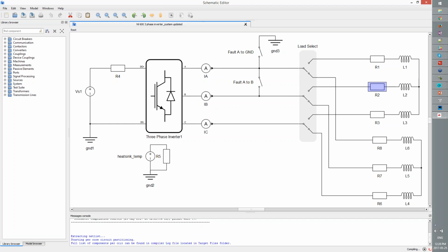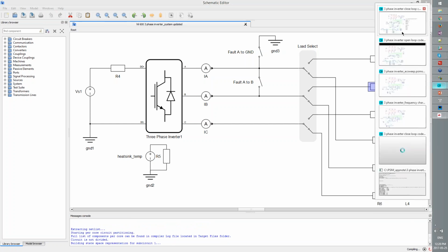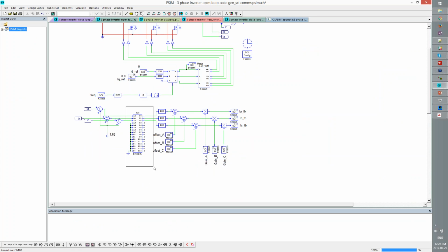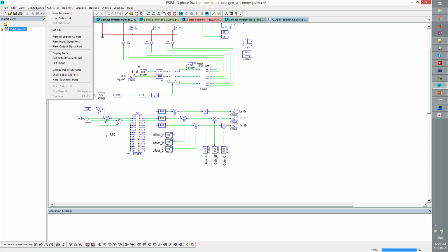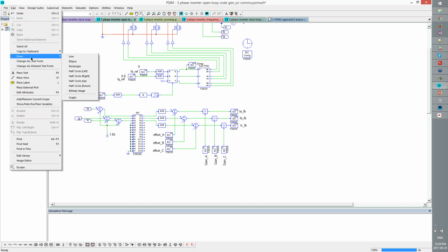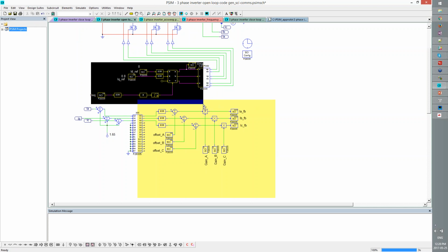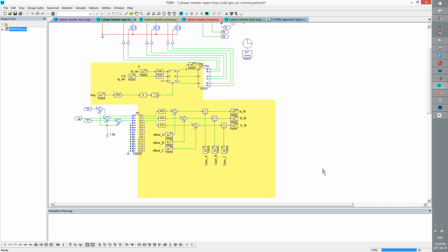When I'm generating the code of the ADC module, do I need to feed a fake signal for AD? Okay. So in PSIM, the question, this ADC block. What PSIM knows to sample the ADC, or the generated code knows to sample the ADC, is when there's a signal connected to it. So if I draw a rectangle here, this is inside of the DSP, this chunk and this chunk. Everything in yellow is inside of the DSP.